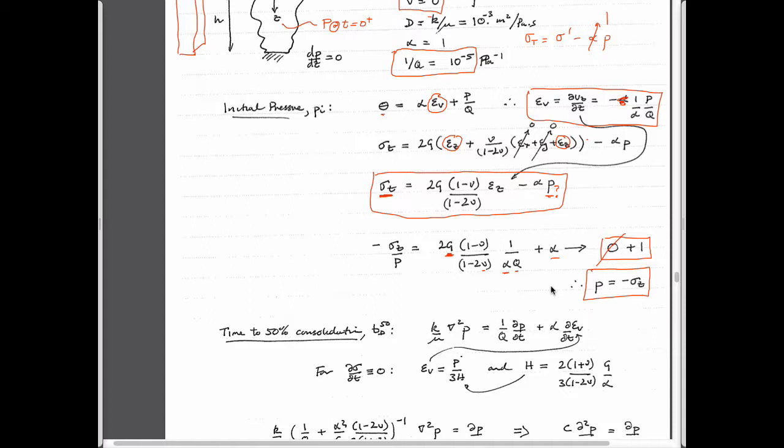So physically what that means is you load it, and the fluid pressure in this block immediately jumps to the same stress. That means if you look at effective stresses, the total stress which we're applying is equal to the effective stress minus alpha times P. So if we apply 1 unit here, and this basically increases by 1 unit, I guess they're the negative of each other just by the terminology, then the change in effective stress that occurs has to be 0 to make that true.